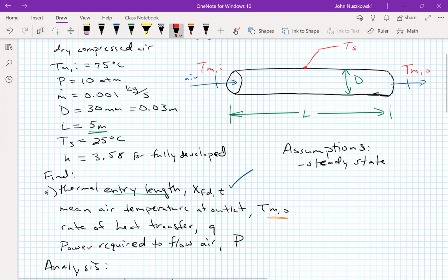What is this right here telling us? We have constant surface temperature. It gave us 25, the surface is 25. So it doesn't matter what else is happening out here, the surface temperature is always staying 25. And since that's staying 25 all along here, and the temperature of the fluid's changing as it goes through, the heat flux would change as you go through. So it can't be constant heat flux, right? And this being held constant, it doesn't matter what's happening in the external fluid side.